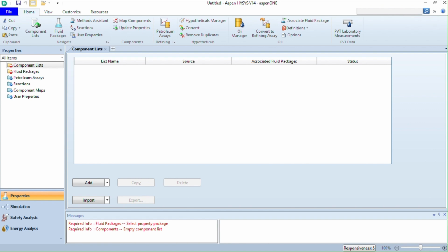So, in this tutorial, a natural gas stream containing N2, CO2, and C1 through NC4 is processed in a refrigeration system to remove the heavier hydrocarbons. The lean dry gas produced will meet a pipeline hydrocarbon dew point specification. So let's start the simulation.